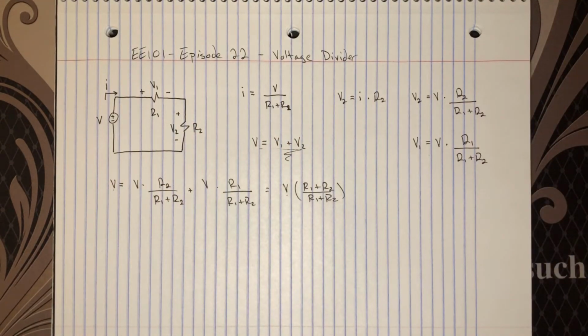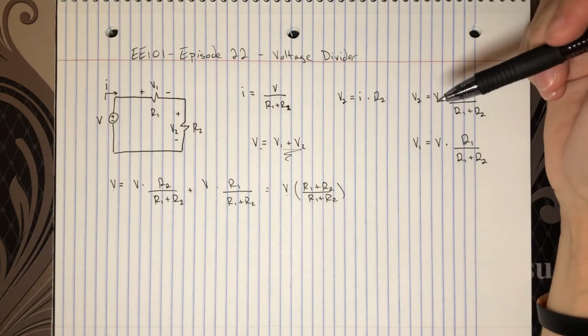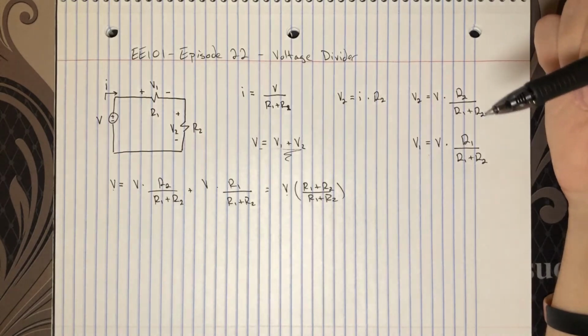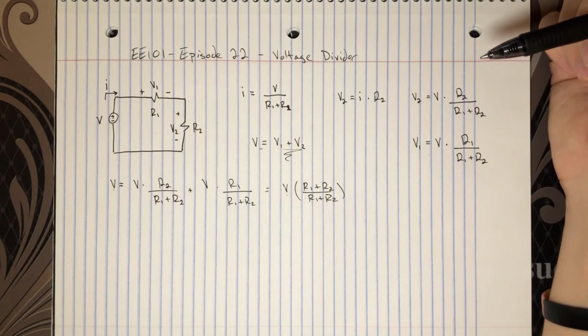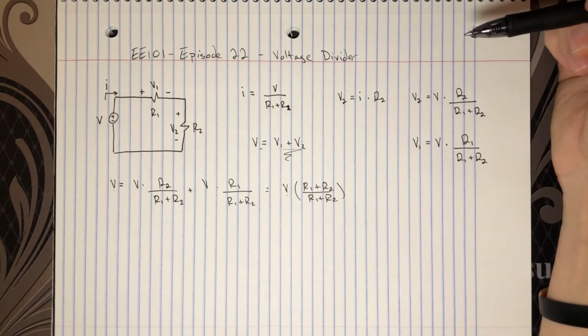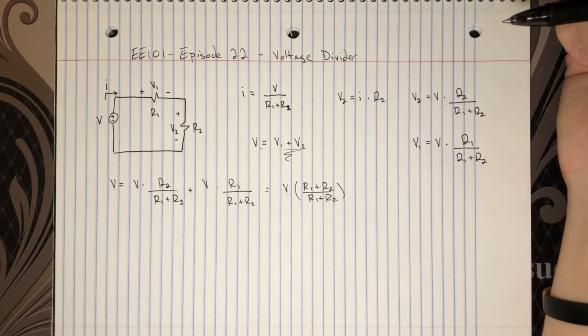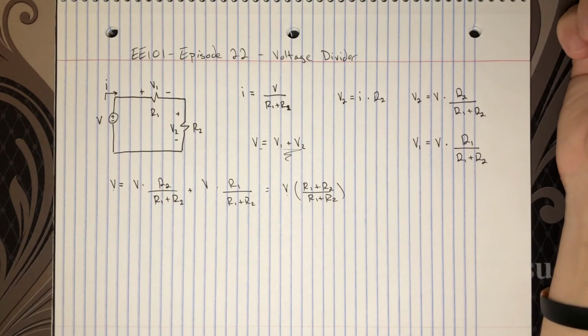So why am I belaboring this point so much? It must feel like I'm beating a dead horse at this point. Well, I definitely am, and if this is your introduction to electrical engineering or the concept of voltage division, it may seem silly, but it's important to realize and just remember this: every circuit you ever work with, whether by design or just as a consequence of the system, will contain voltage dividers, quote unquote, or voltage division.